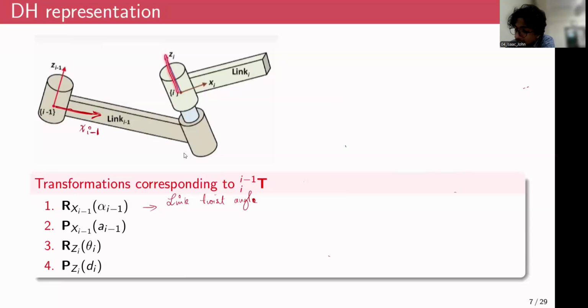So if this is the angle zi makes, I'll just bring this zi vector over to the zi minus 1, just for representative purposes. So if you can see this blue line, this is the direction of zi, and this alpha i angle corresponds to the rotation that you have to make about xi minus 1 axis so that zi minus 1 and zi will be aligned, right?